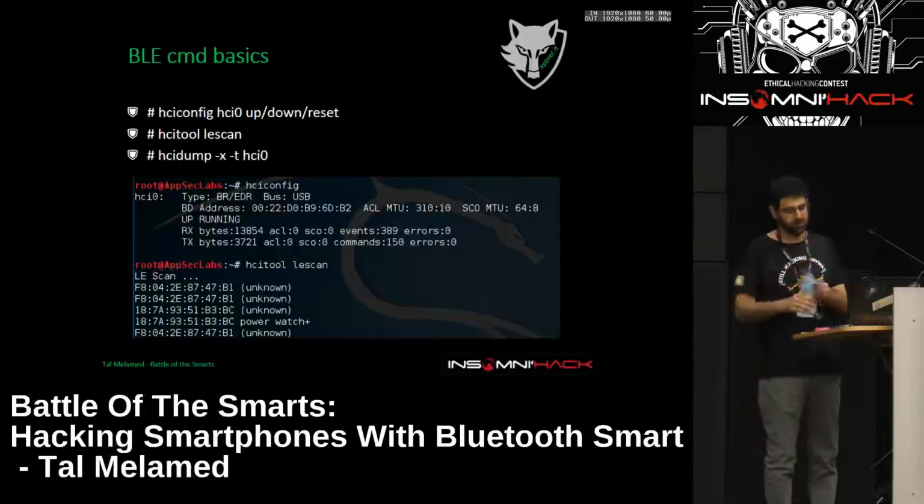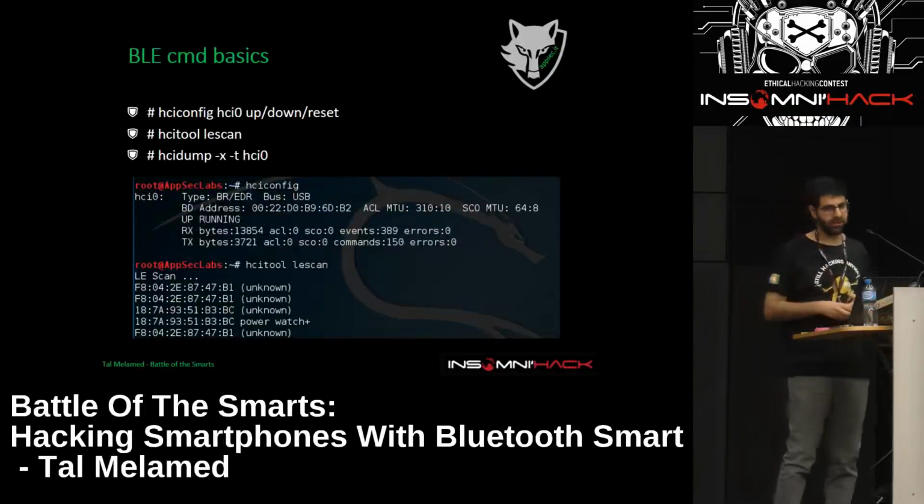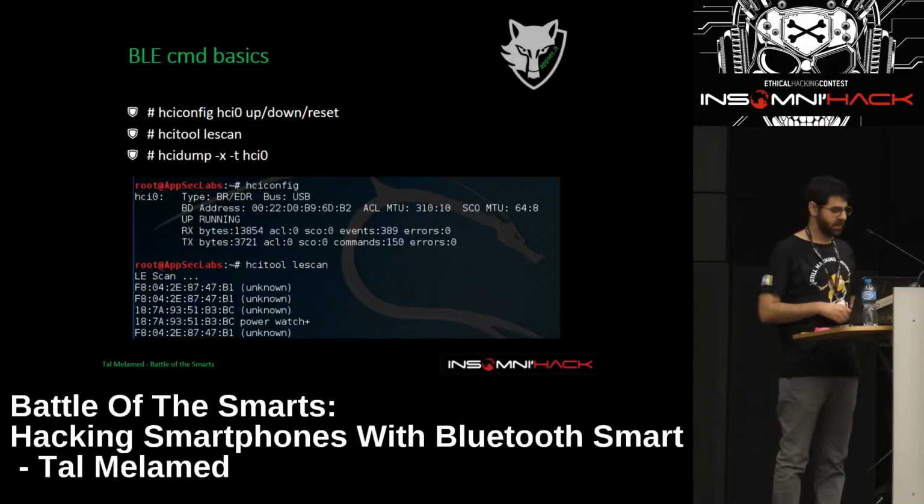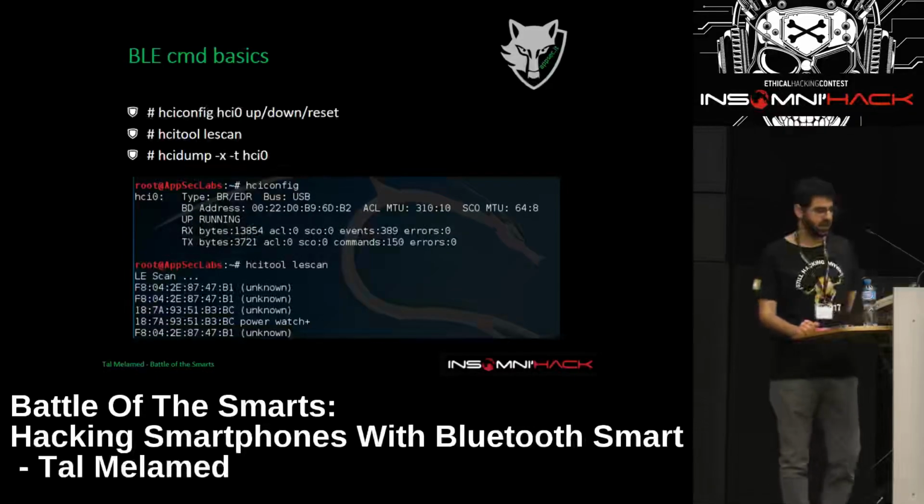Okay, there are a few tools that are built into the environment. Of course, after you install all the BLE libraries, there is hciconfig, where you can configure your interface. hcitool has many functionalities. To scan devices, you use lescan, and there is hcidump, which gives you a dump of the communication over a specific interface. These are examples.